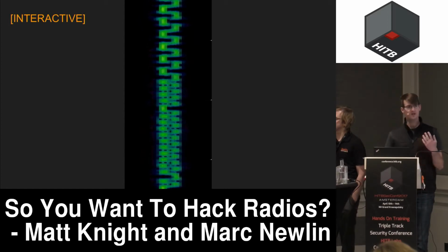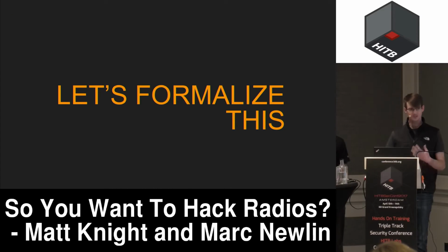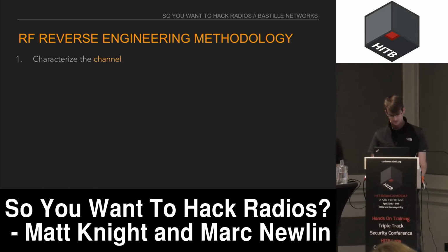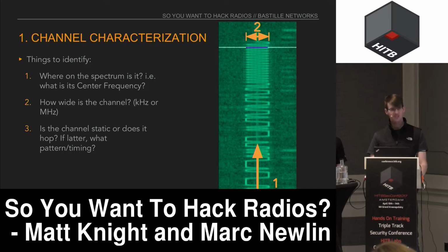But we kind of just talked through all the core concepts that we're going to need to reverse engineer these systems, right? So let's formalize this and start to put it into a process that we can apply to these signals. So step 1 to reverse engineering a wireless signal is to characterize its channel. And that's basically find out where within the spectrum the signal lives. So there are really 3 things we're looking for with this.